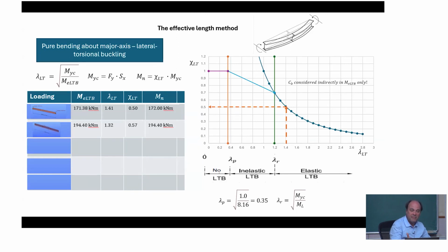For that, we have a somewhat lower slenderness, so of course we will have a somewhat higher reduction value, and a higher LTB bending strength. Then when we move the load to act on the top flange, it has a detrimental effect. As we know, the lambda increased from 1.32 to 1.6. For the 1.6, we will find the lower value of the reduction factor.